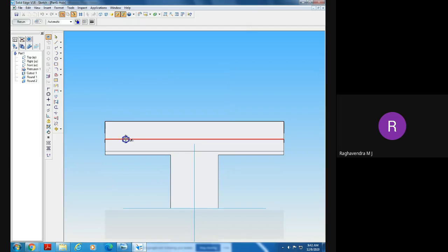Then somewhere, don't click on this red color line here. Somewhere here you place it. Here I don't have any disturbance. Here it will come as tangential, and later we cannot change the position. Therefore, still move in the upward direction until that red color line as well as that tangential symbol disappear. Move it upward. Place it now.